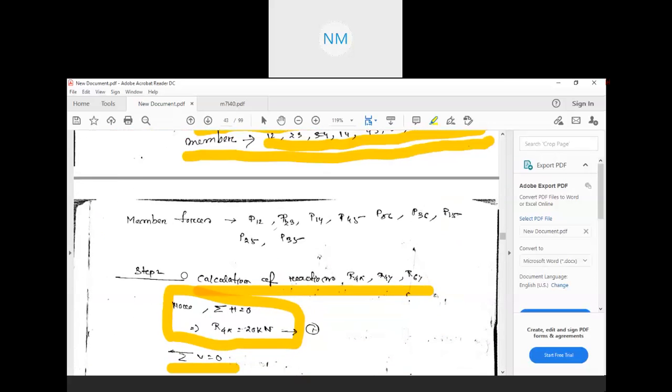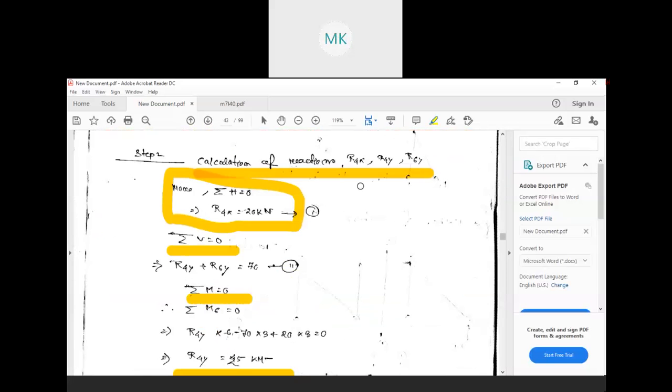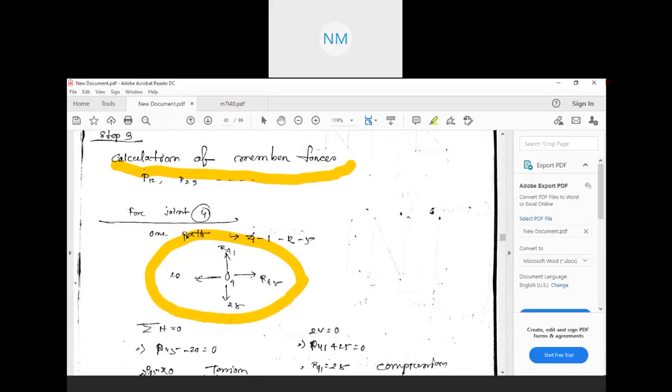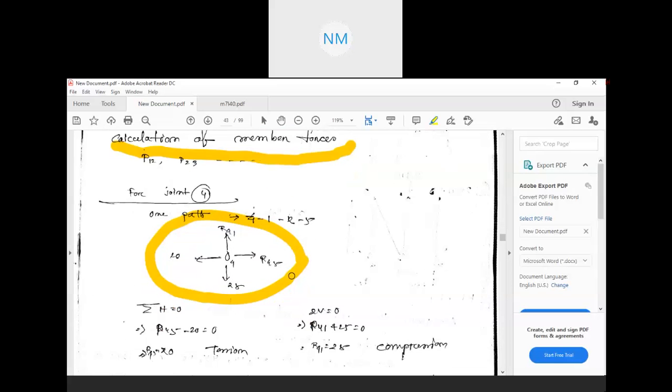Okay, fine. I think you have understood how to find out the reaction. Up to this part it is okay? How we are calculating this reaction? Okay, fine. So when you consider this joint, you are taking... Sir, look at this 20. It should be acting compressive, but you drew the arrow outside, and in the calculation we gave minus.